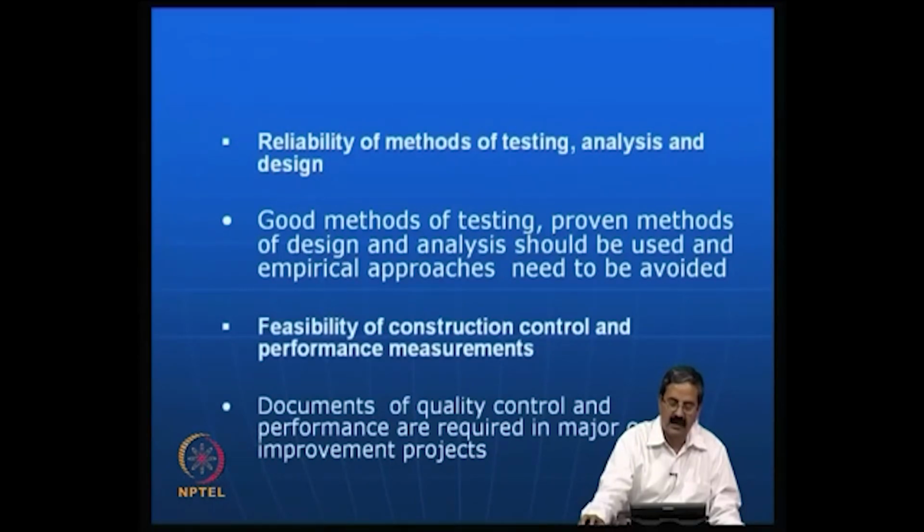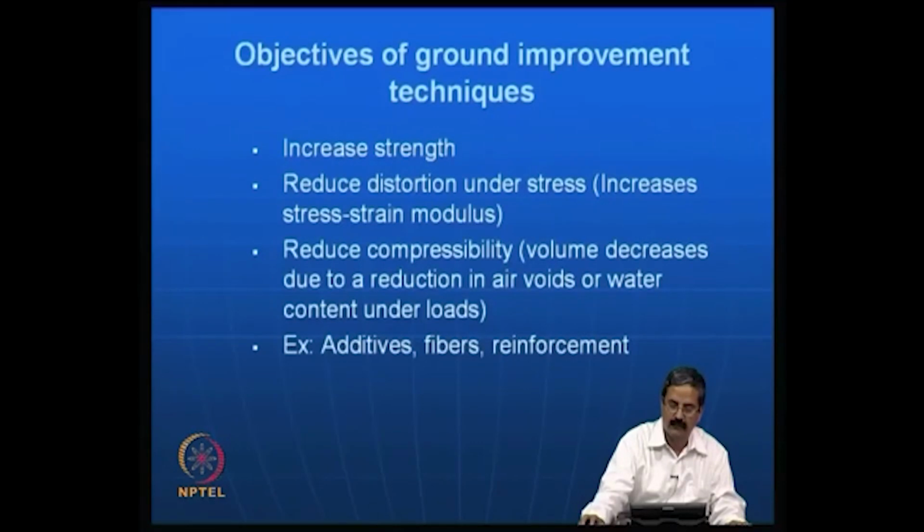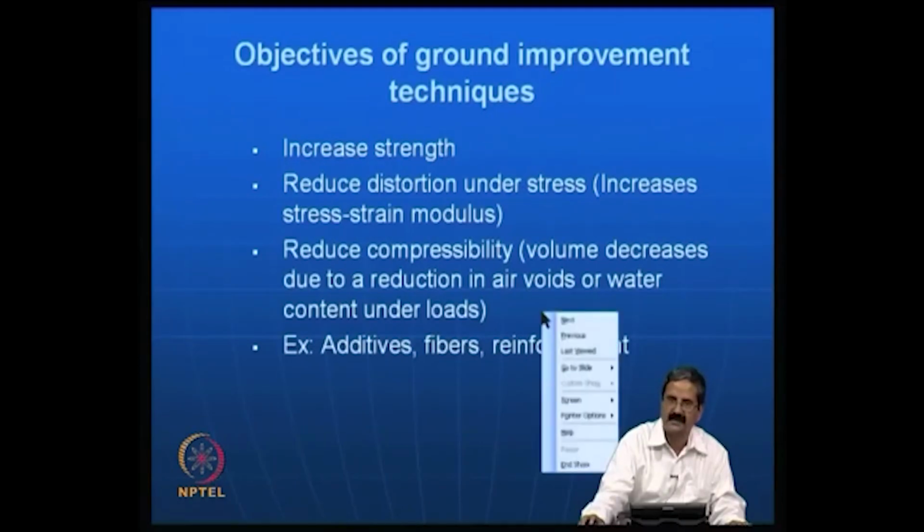So for example, compaction control: at what spacing you should take samples, or what type of test, like say the sand replacement test, should be really specified, and then they should be used in a lot of ground improvement projects. So this is another point that I would like to cover next class.